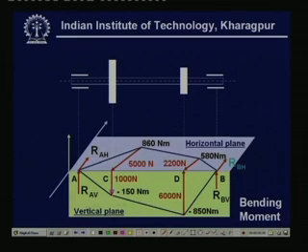So, this is the loading as far as the vertical plane is concerned. Now, if you consider the horizontal plane, the total pulley force was 1000 and 4000, so the combined 5000 is coming like this, and the gear force onto the pinion in this direction was 2200. So, both are coming downward here, whereas in the other plane one is downward and one is upward.